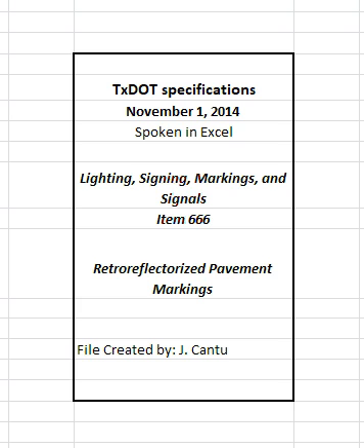4.5.2 Portable Retroreflectometer Measurements. Take a minimum of 20 measurements for each 1 mile section of roadway for each series of markings, i.e., edge line, center skip line, each line of a double line, etc., and direction of traffic flow when using a portable reflectometer.